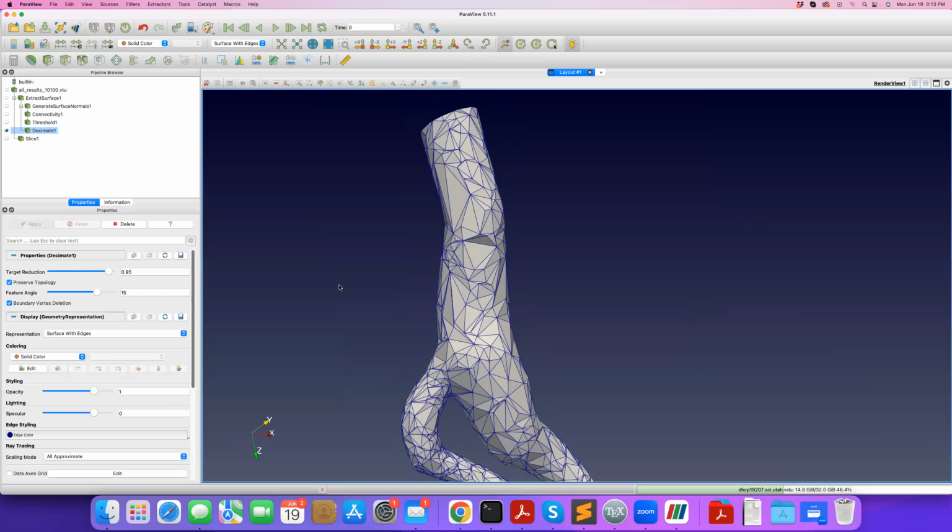And the last thing I want to talk about is plot over line. This is another very useful thing. Here you can define the 2 points that define the line, or you can just drag these 2 points to where you like them to be. Let me make sure they're both inside, move them along. That is not inside yet, go in, okay. And if you like, you can make this opaque so you can see where your line is.